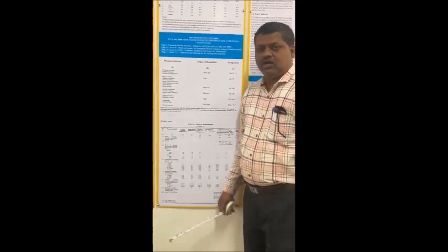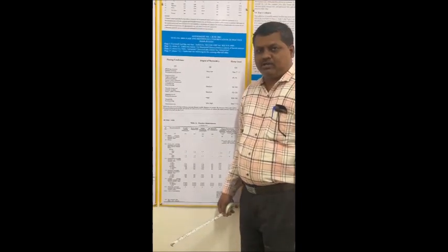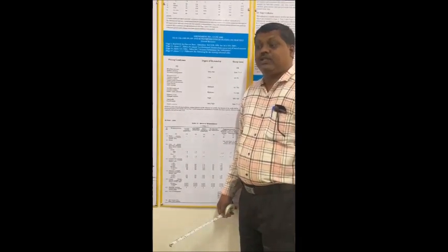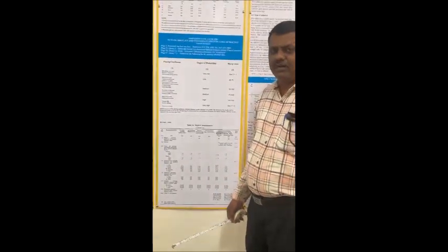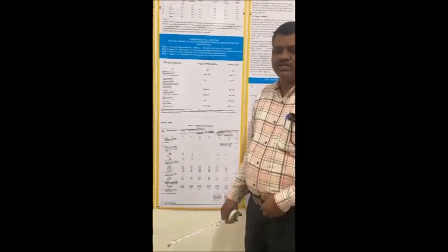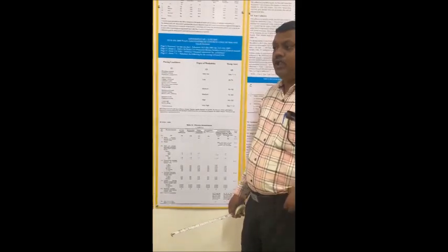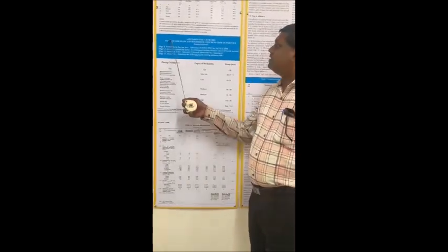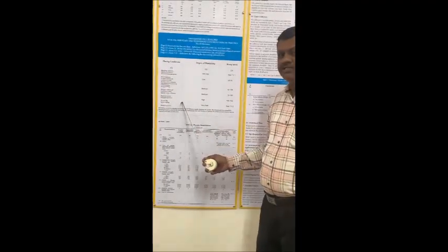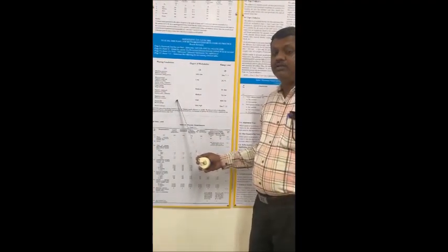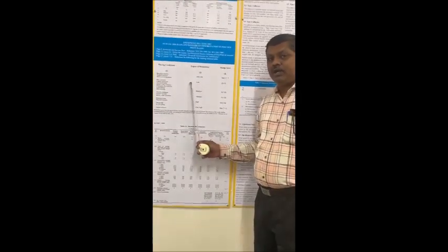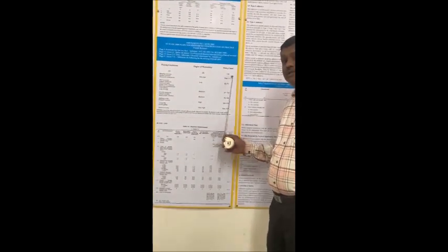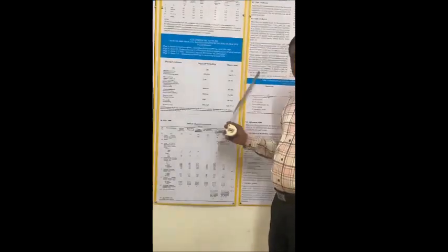Welcome to the session. Workability of concrete, placing conditions with the nature of concrete. In the earlier video I explained the nature of slump, which is the first or primary test of workability. Now as per IS 456:2000, for different placing conditions and different types of civil engineering works, how much workability is required, what should be the degree of workability and the value of the slump. These things are specified in IS 456.